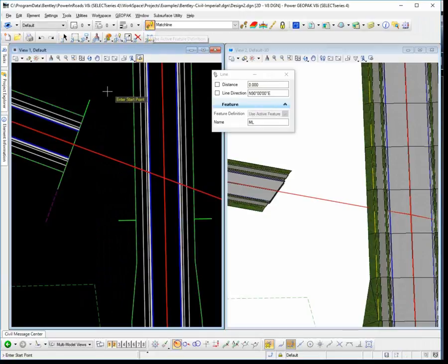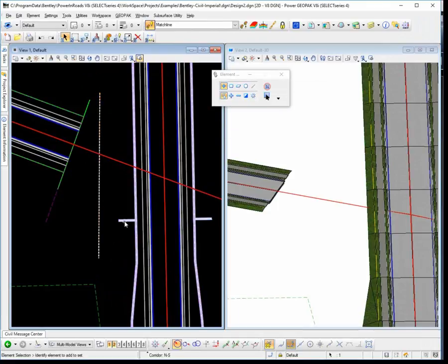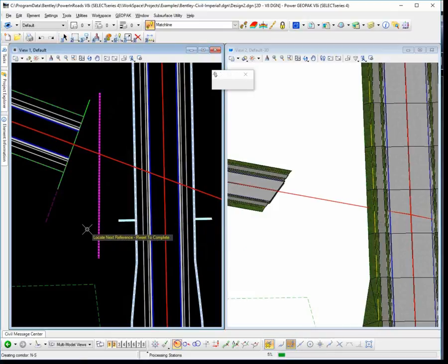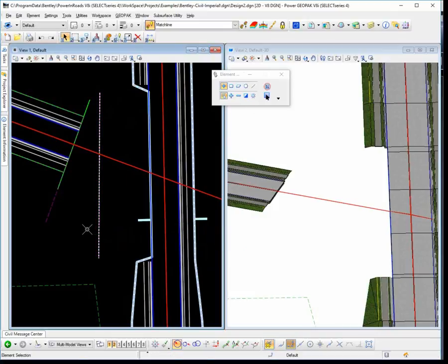And so if I just go place a match line out here in the general area, notice it doesn't do anything, so I have to go to my corridor and add that as a reference to my corridor. So you're in your corridor, add reference, and we'll select that, reset, and then that'll go ahead and have everything stop drawing at the edge of pavement. So then I can place my civil cell and not have to add that civil cell as a clipping reference to the corridor. You want to try to avoid adding clipping references to your corridor as much as possible.